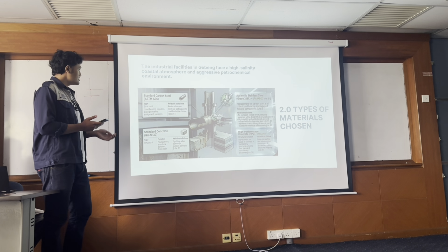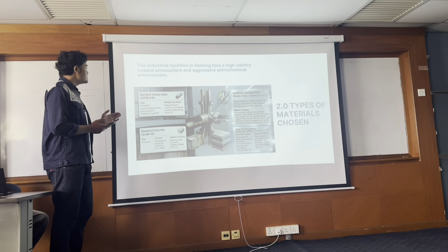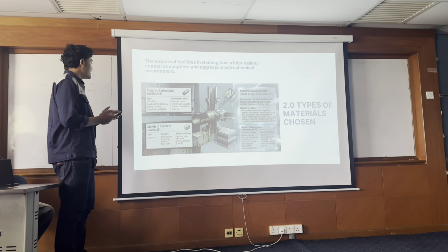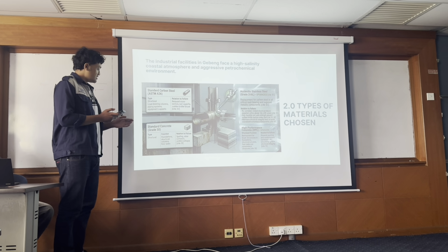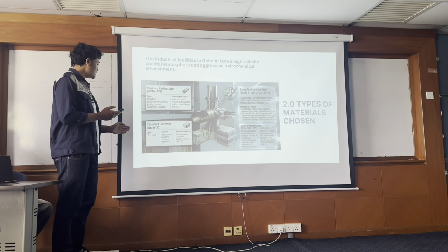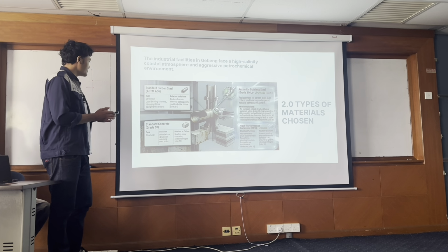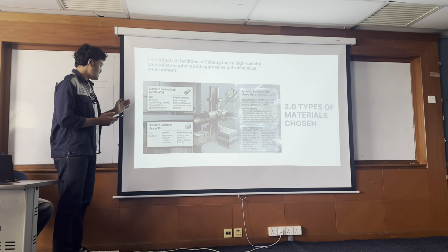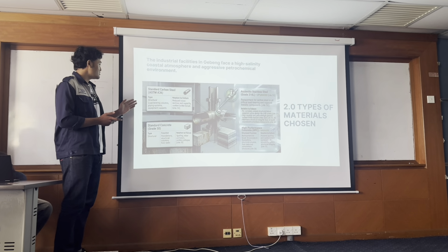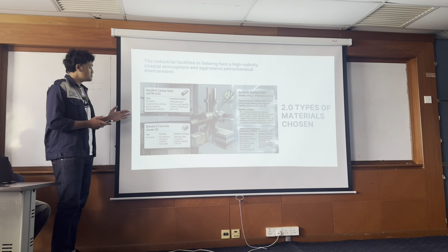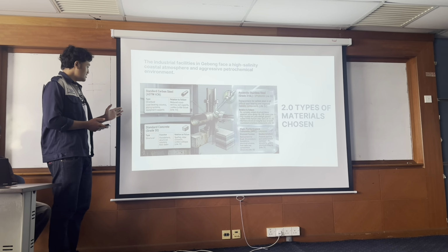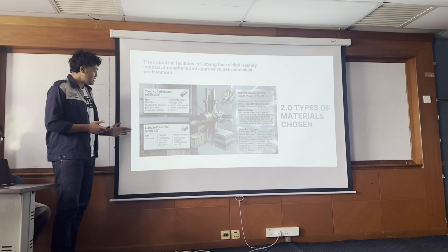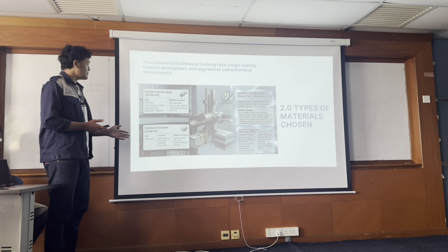Traditionally, the facility uses standard carbon steel, which is ASTM A36, for piping and support structure, and also standard concrete grade 30 for the foundation. For standard carbon steel, the type is structural, and the function is load bearing column, piping system, and also equipment support. For the concrete, the function is foundation structure, column, and also floor slab.